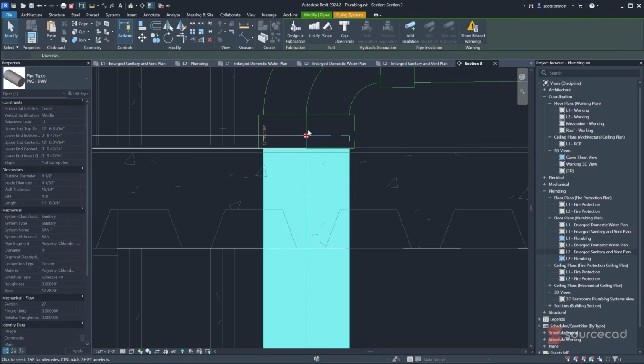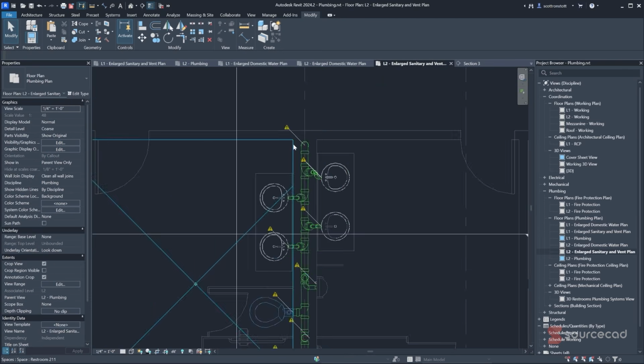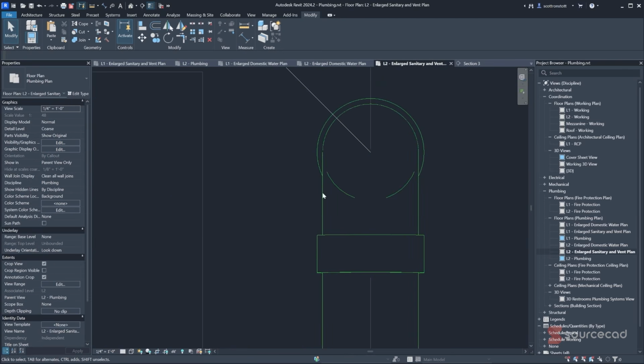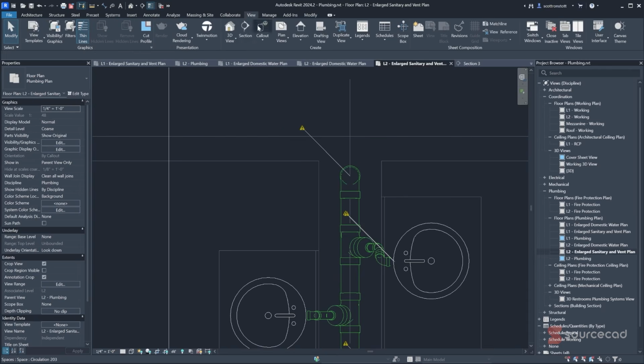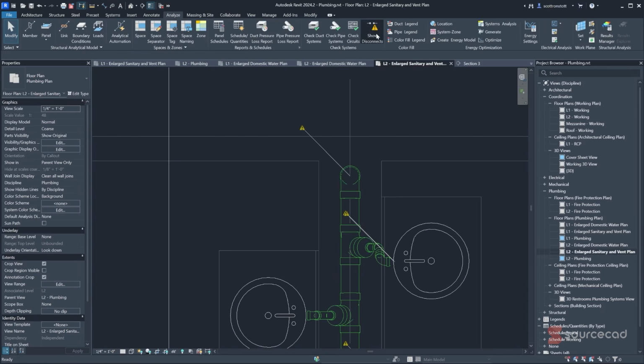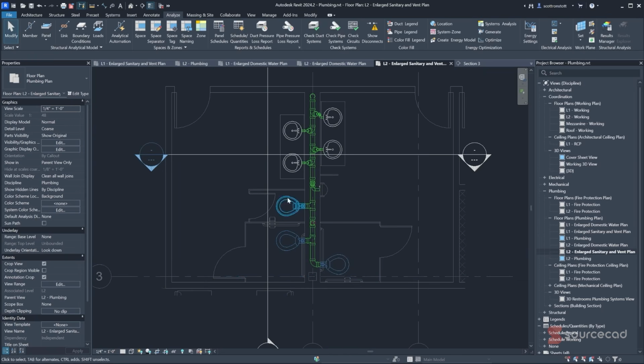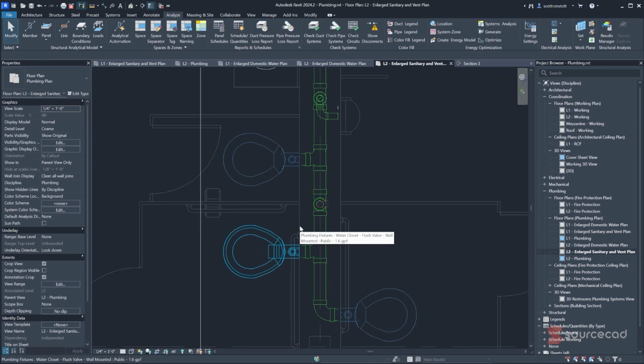It might also be misaligned in the other direction that we can't see here. So let's look in the plan here. And again, it's such a micro difference that I can't even perceive it. So I'm going to disregard it. I'll go to Analyze and turn off Show Disconnects. So I think we're good all throughout. The only thing outstanding is the vent.